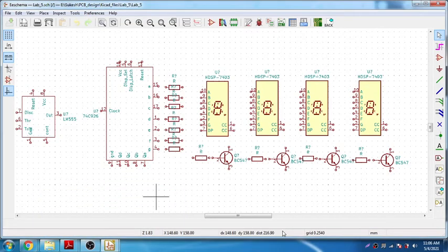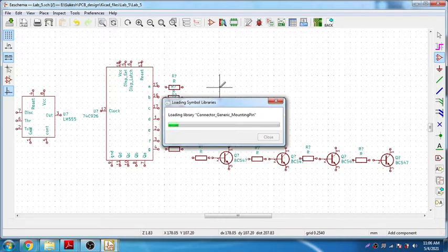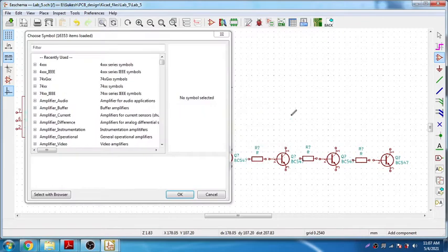Yeah, so what I will do is I'm going to delete all the segments, and instead I'm going to put a new device in that place. Later I found there is a similar device available with pin numbers 3 and 6. Even the data sheet which I have for the display, in the component data sheet, I have the same 3 and 6. 3 and 8 are actually common cathode connected to the VCC. So let me have a similar device.